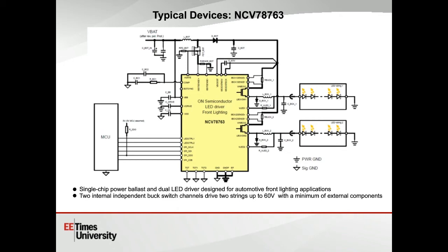And so it's highly efficient. This device includes typical efficiency of up to 94%. It includes PWM dimming, which is under the control of a SPI interface from a controlling microcontroller. And as we mentioned, this is a high-function device, so it includes multiple diagnostic modes, for example, thermal protection, temperature monitoring, and the detection of both open and short circuits.